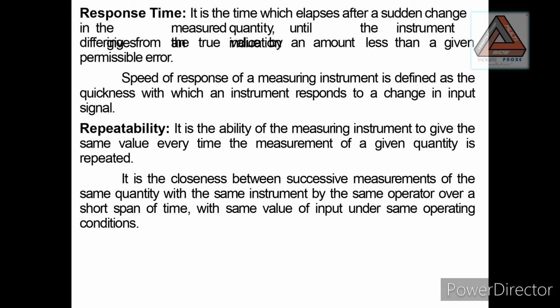Variations in geometry and surface finish of the measured part directly affect the measuring system repeatedly. Compressible materials like plastic or nylon present a different type of problem, as any gauge pressure will distort the material. This can be avoided by fixing the gauging pressure as suggested by the industry, so that everyone will get a uniform result.